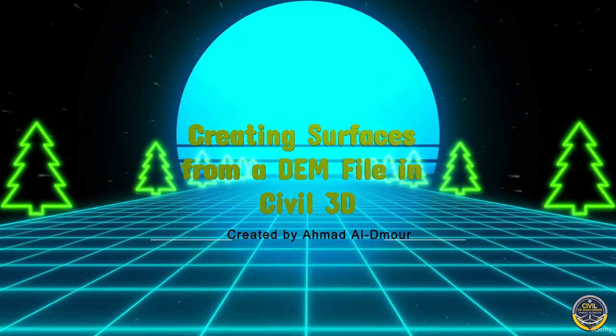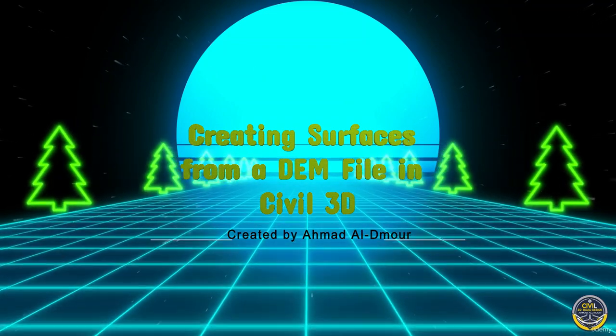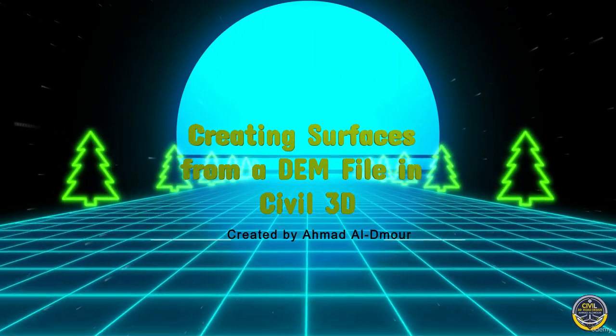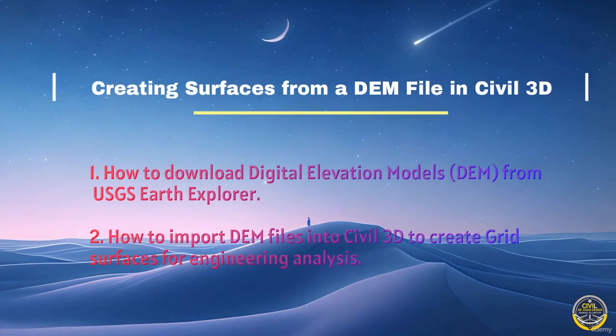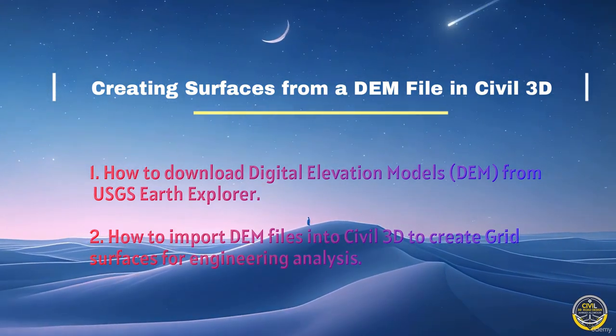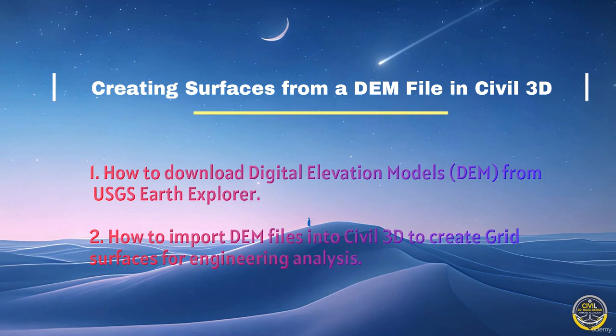Welcome to this lesson in creating and managing surfaces in Civil 3D. Surfaces are the foundation of any civil engineering project. In this lesson, we will cover two key workflows. One, how to download a digital elevation model, DEM, from USGS Earth Explorer. Two, how to import DEM files into Civil 3D to create grid surfaces for engineering analysis. By the end of this lesson, you will understand the difference between TIN and DEM surfaces and when to use each of your projects.